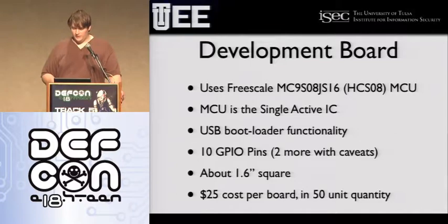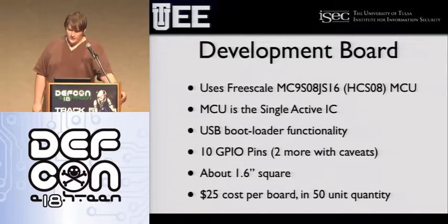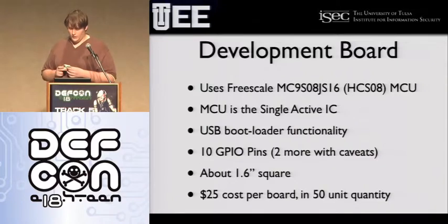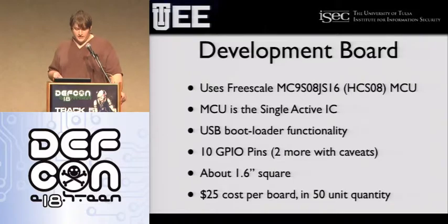But it's based on a pretty simple Freescale chip, similar to a chip that was used on the badge a couple of years ago. There's only one chip on the development board, and you can load code on it over USB, still using that chip. It's a pretty unique device, so we decided to build our kit around that. And you only have 10 general purpose I/O pins, but for a learning tool, we thought that was enough. And it's, again, dirt cheap. We made 50 of them for $25 each.